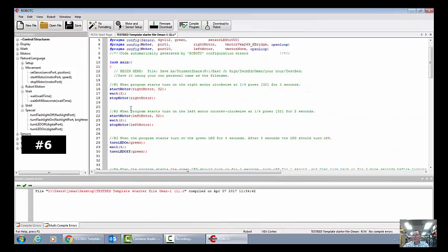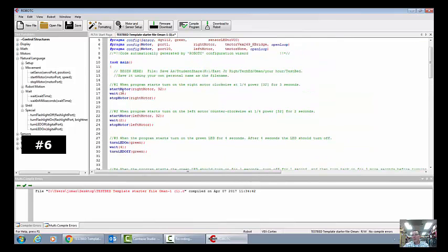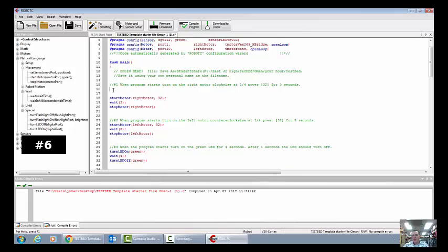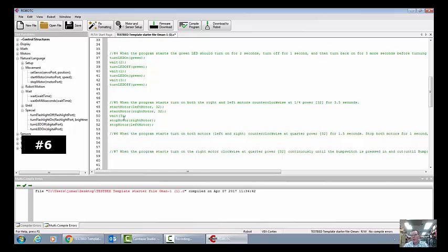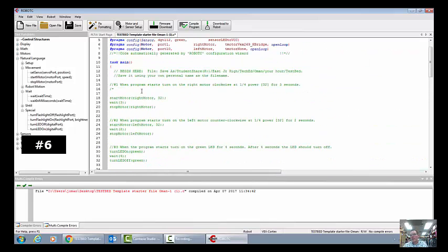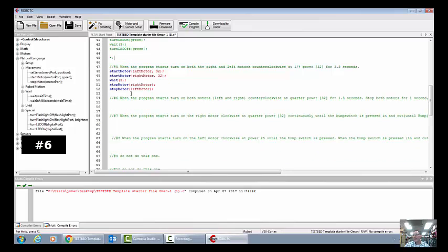Okay, if you're tired of watching all of these programs run, you can actually do pseudocode by adding in right above the first problem. You can do a forward slash and an asterisk. Right there, that greens out everything after that, but if I want to run this one, I need an asterisk slash right there, so these up here are not showing, only the one I'm working on right now. Alright, then I can download that and watch only number 5 run.